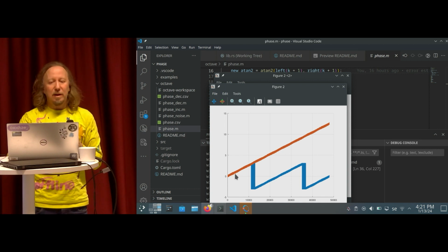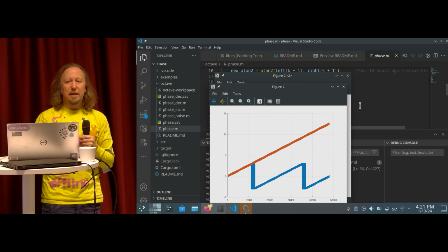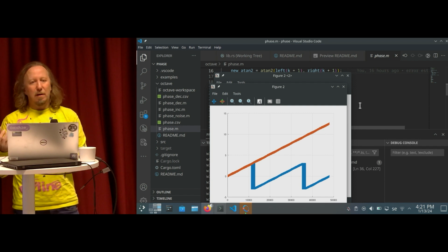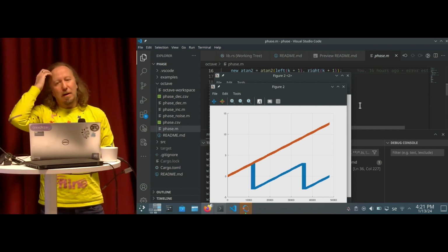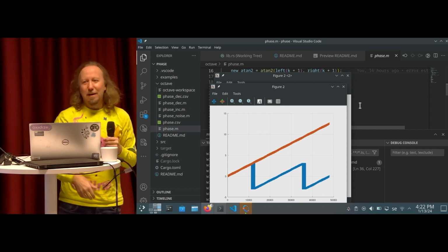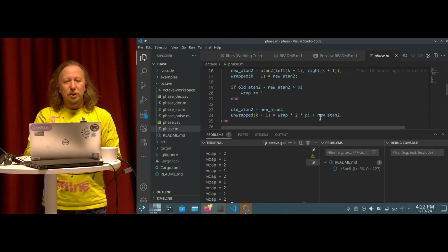So on average, if we make a bit of low-pass filtering here, it would look perfect again. So that means that it's really robust. 25% noise would be approximately 2 bits. If you are sampling with 2 bits, then you will get that bad signal to noise ratio. But we can push it.